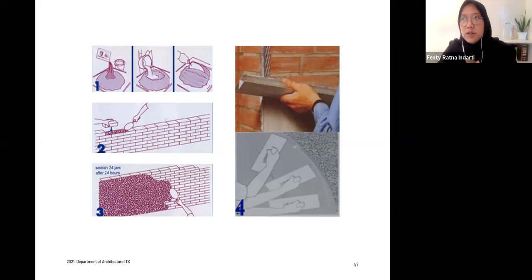Some parts of the wall, such as in the bathroom and also the kitchen, have another layer which is called the water resistant layer. You put it before the painting, and usually it will give protection towards the water, so that it doesn't create fungi, or maybe something like the lump that I mentioned before. So that's why it depends on the location of the wall, whether you need additional types of materials such as waterproofing or not. It depends on the area that you are concerned about.